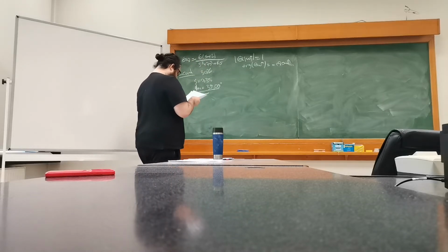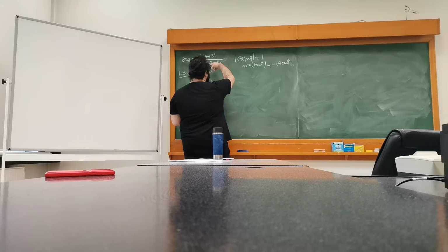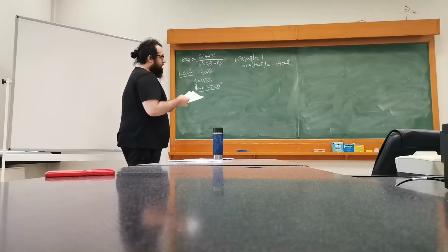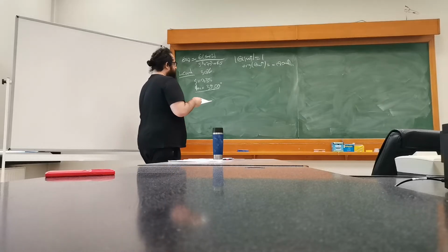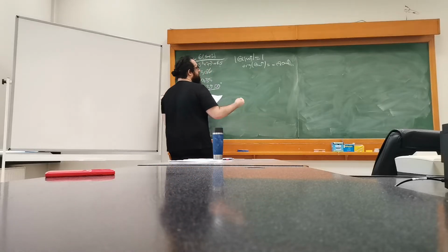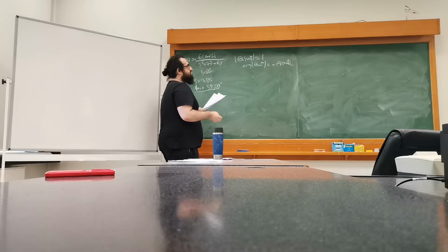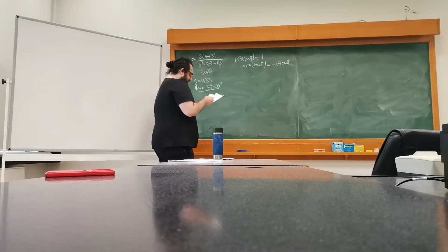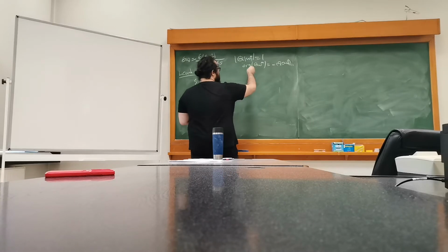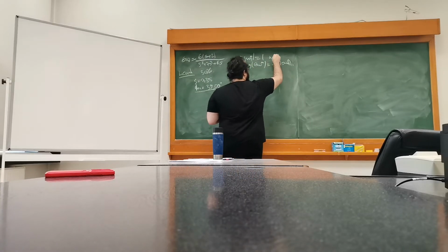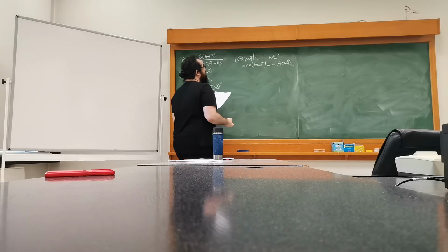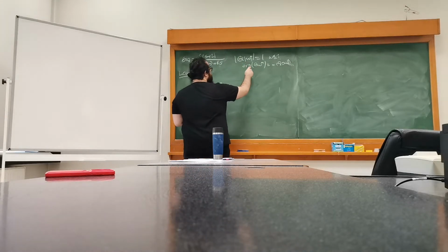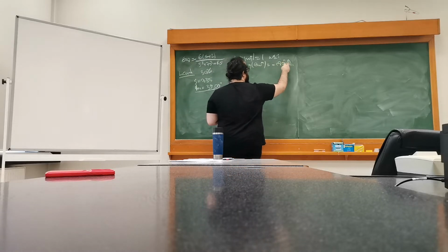So yeah, if we look up the gain condition, I'm not going to use the symbolic equations here because it will take too long. But I assume that we have a Bode graph, so I'm going to look for 0 decibels, or gain equal to 1. And at that point, I'm looking at the frequency. So at what frequency is the system's gain equal to 1? That's basically the question. Then I'm going to look for the argument, and then the difference from 180 degrees.